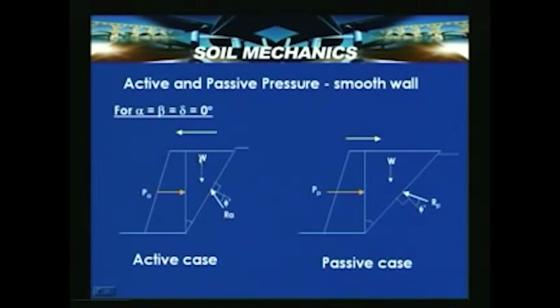So, in this case, this particular portion is completely plastified, where the plastic equilibrium prevails, and the rest of the portion is under elastic equilibrium conditions. So, Pa, which is horizontal here, can be found out again by substituting this, and the coefficients change into the corresponding Rankine's coefficients.